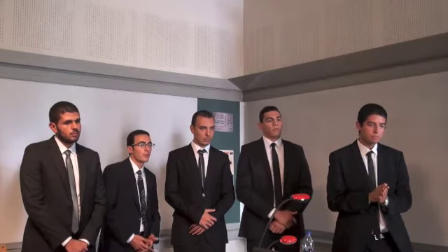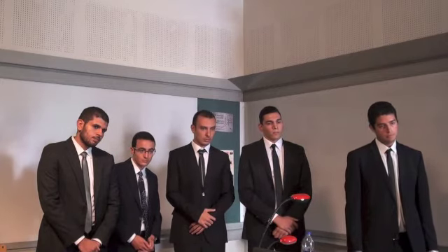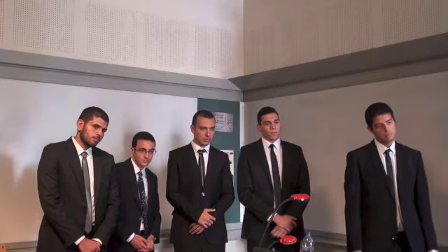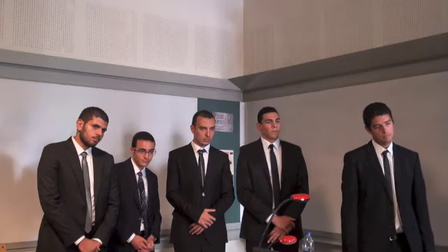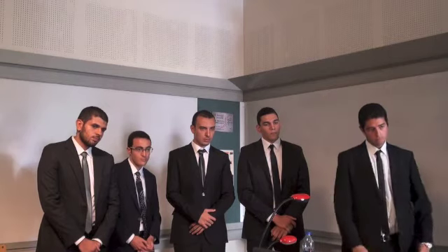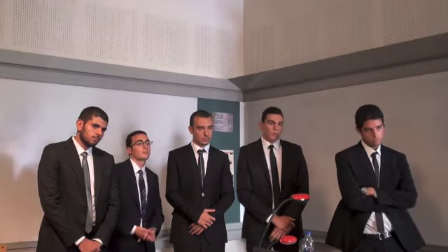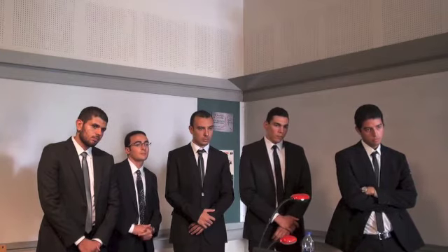Like moving load or stationary load? Both. So if both, that's why I'm asking. If you sustain traffic, for example, your test is not to be concentrated load. You have to test the repetition of this load, not only the magnitude of the load. So this is my question. The function of this slab, for what? For trucks to move on it, or only for heavy loads on it?